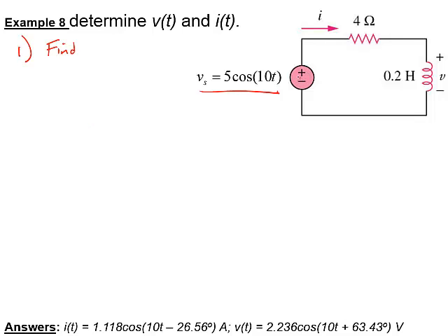Yes. CircuitLab is nice, but it doesn't do these fixed-frequency analyses very well, although I haven't played with it that much. CircuitLab kind of wants to do a frequency sweep when you have an AC circuit, so you can see the frequency response. It doesn't do so well at single frequencies, and it doesn't really tell you the phase, I think. But CircuitLab does have these components for alternating current signals. It won't be plus or minus, it will be a squiggle.